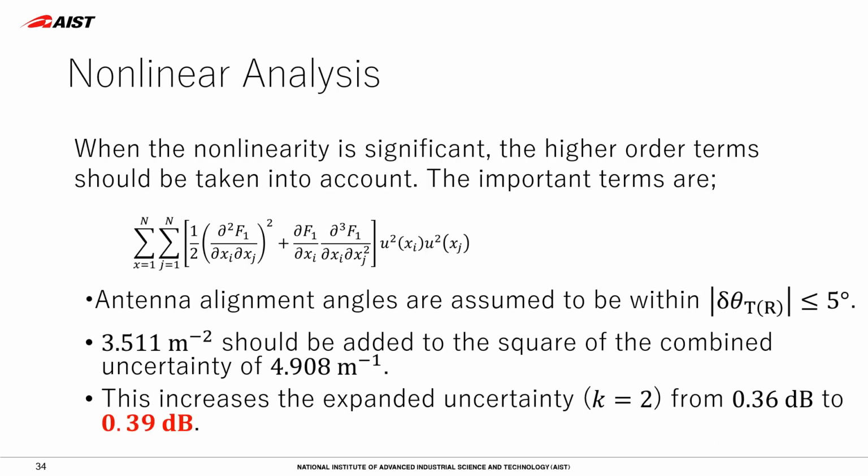So far, uncertainty due to the angle is not included in the analysis, since we know the effect coming from the antenna polarization mismatch is small. However, when the variation of angle is relatively large or high-gain antennas are used in the measurement, the contribution of the angle should not be neglected.